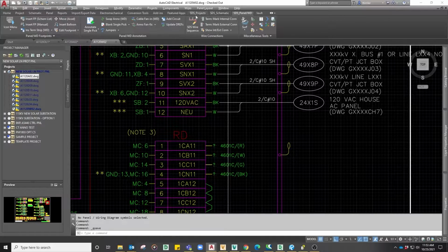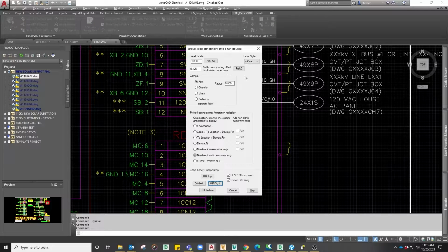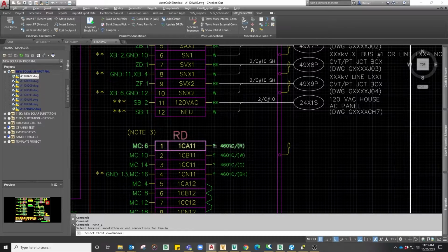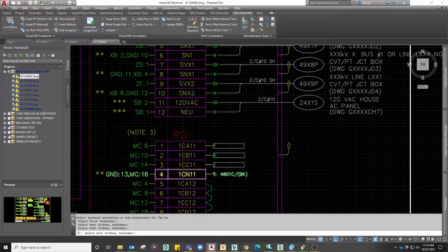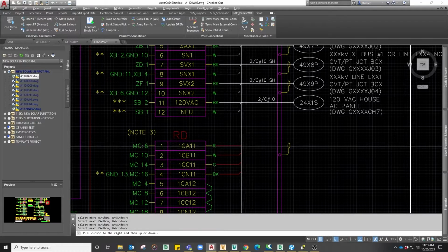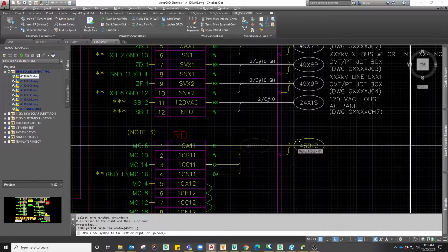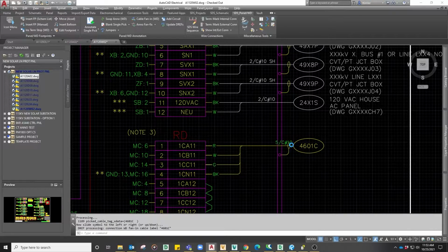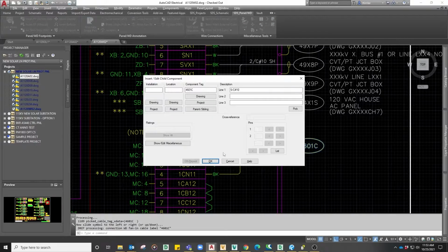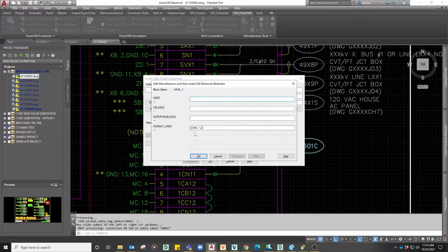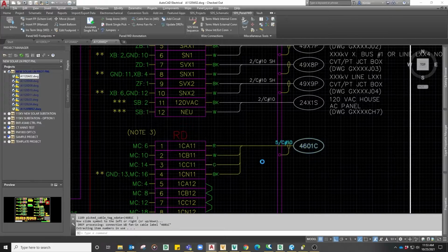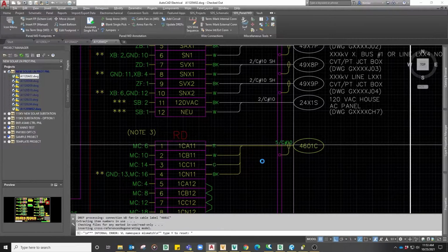Once that's completed, I'll go to the SDS Panel WD tab and select the cable tool and go ahead and draw out this cable. It's a very small list of commands that you have to learn. Once that's drawn in, I need to verify that the format dref is the same as the breaker end of the cable. And I know I have to put %D there, that wasn't there. But that's the only variable I need in that field, so I'll go ahead and hit OK.